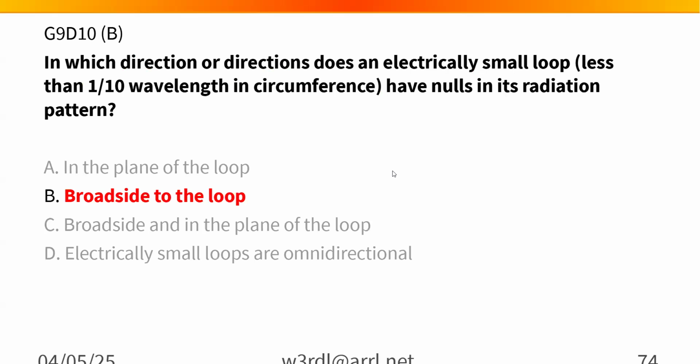So which one is this one or this one? They're both broadside. Yeah, but he was talking about direction finding. Oh, because it's got two nulls. Then use two magnetic loops a half wavelength apart, 90 degrees out of phase. That takes two people, whereas if you get a cardioid, it takes one person.